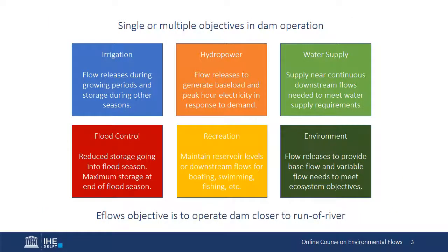Before we look at the technologies, let's put ourselves briefly in the mind of the dam operator to consider different motivations for flow releases depending on the objectives and purposes of the dam and reservoir. Also consider that for a storage dam, the operator is thinking about managing both the reservoir level as well as the releases. For a run-of-river dam, the operator is more dependent on the incoming river flow. Withdrawal points for water supplied by the dam may also be at the dam site itself or further downstream.